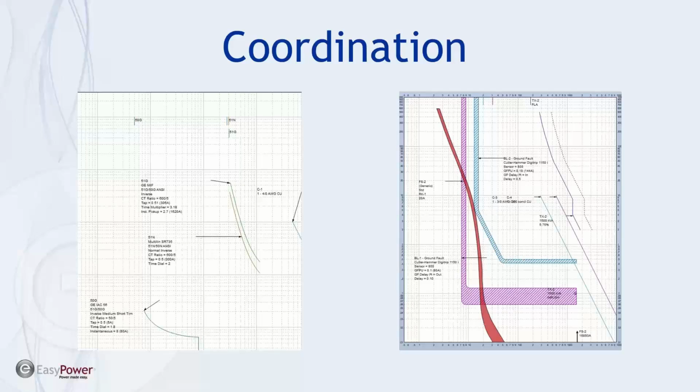And then at the same time, we're also isolating or protecting one of the other loads with a fuse, and we've got the N setting, the corner clipped off of the main ground fault breaker, to allow coordination between the fuse and the main breaker.